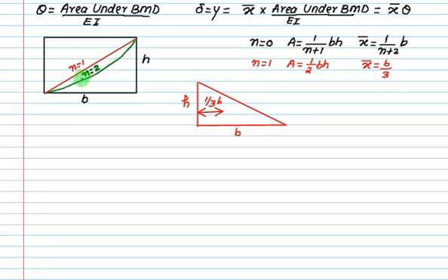We have a parabola here, but this parabola is marked like this. So is this area less than the triangle area? This area is less than the triangle area. For this spandrel, I use the word spandrel, where the curve is below the triangle, n equals what? 2. So what is the area? 1 by 3 of BH.